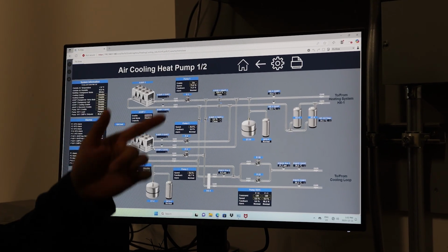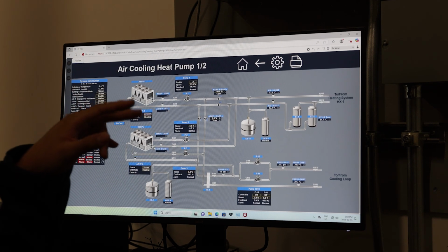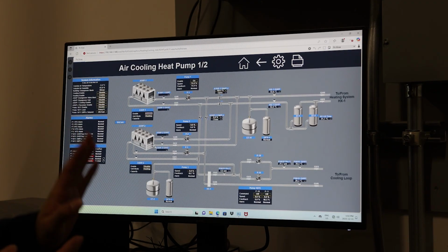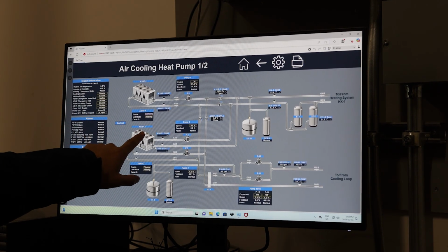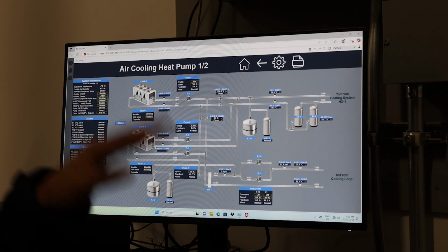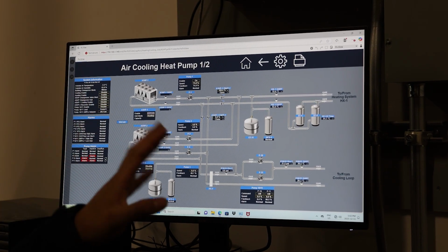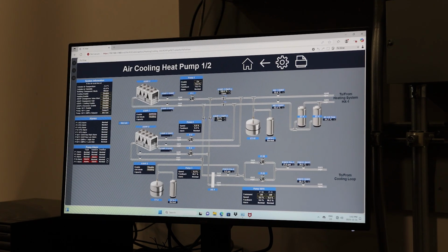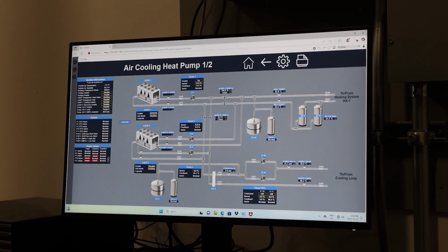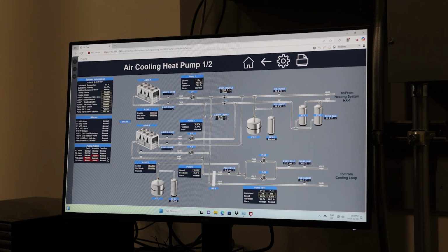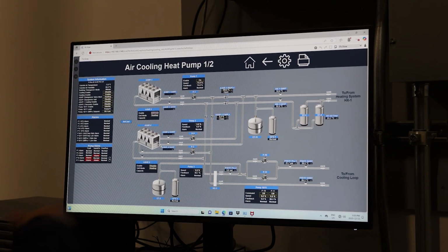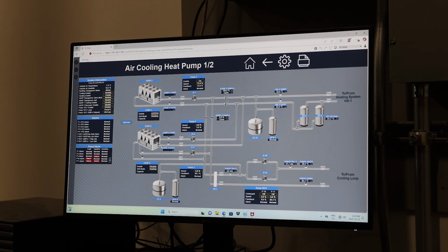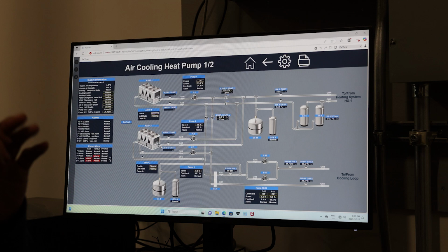Air source heat pump 2 is always doing heating and cooling together. Regardless of whether air source heat pump 1 is doing heating or cooling, air source heat pump 2 is always doing the cooling and the heating at the same time. In the winter, this gives extra heat. In the summer, this gives you extra cooling. So that one's like the main. It's always heating and cooling together, because it collects the heat from the cooling loop and dumps it to the heating loop. It's so efficient. All the suite fan coil units have their own heating loop and cooling loop, individually.